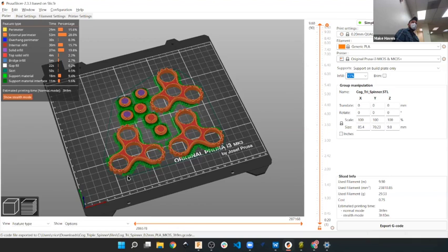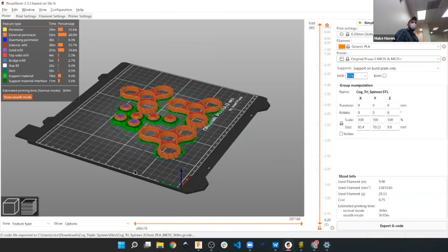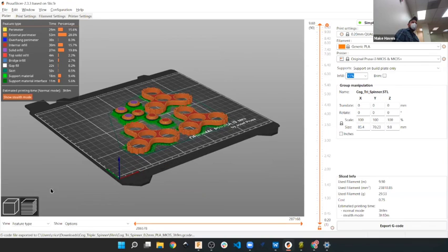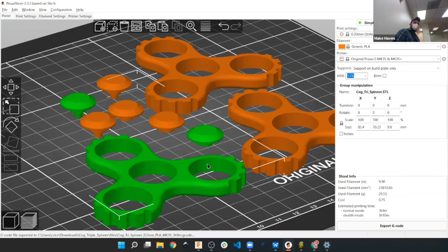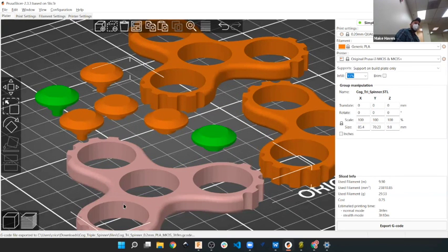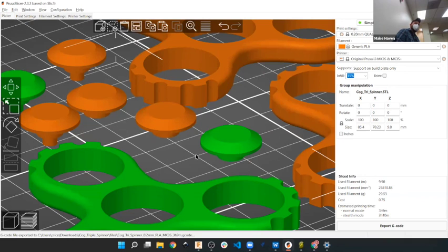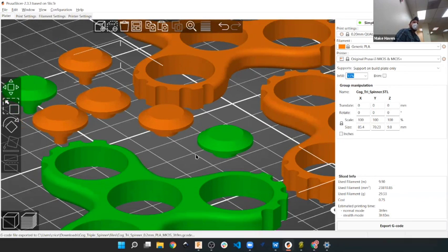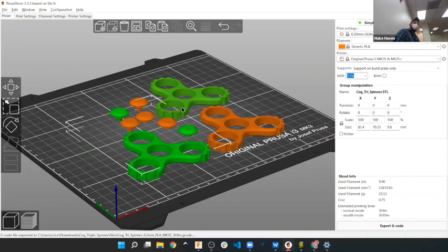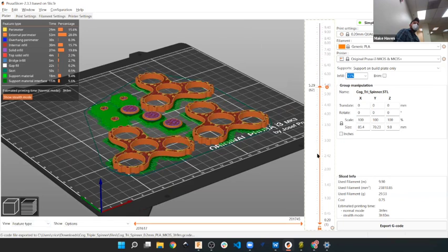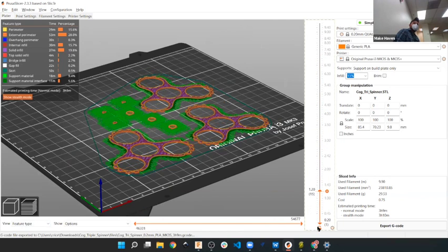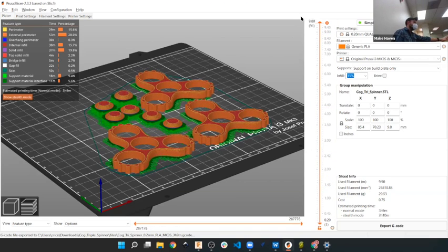Here's Prusa Slicer. There's my 3 fidget spinners, the things that are in the room. These were designed like this, and here's the 3D model, the 3D shape brought in. Those are STLs. If you look at them really close, you can see that their shape isn't super well defined. There's those rectangles and things on there. They're not perfectly smooth. But the slicer takes this geometry, which has not got any detail, and turns it into this, which is all of the different cuts and movements that it takes to make the 3D print. You can see all of these different layers. There's the first layer of the print, and then it goes up through the 3-dimensional shape, laying down layer by layer from the 3D printer.